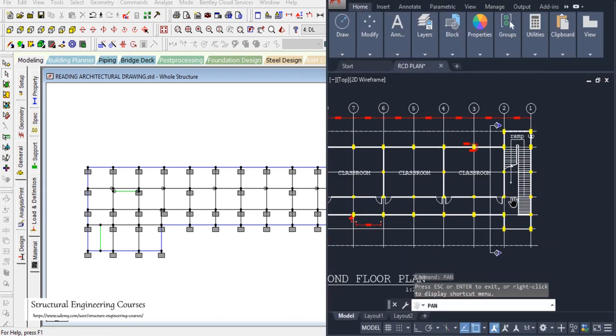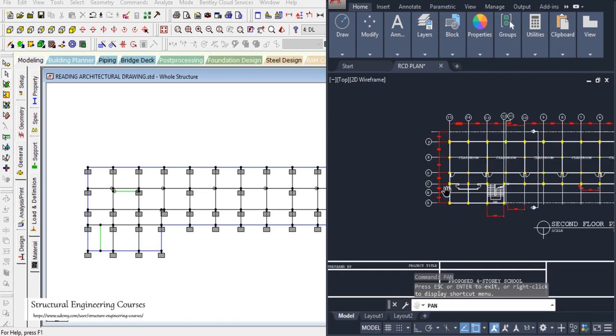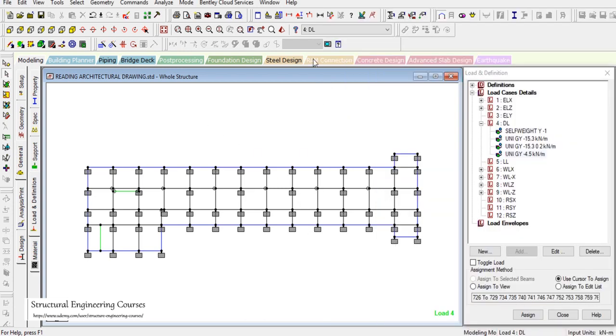Here we can see that the staircase dead loading needs to be considered, and the dead load due to slab also needs to be considered here. Considering the spans are very short, in the range of 3.5 to 4.5 meters only, we can take a 150 mm slab comfortably for this type of arrangement. And the slab is also two-way here. Here also we can see that this span is also a two-way span.